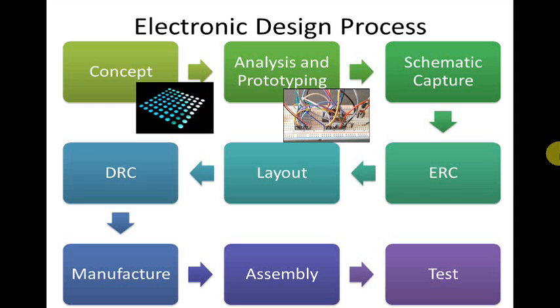This is where we look up the parts we want to use, we breadboard it out, we prove that the circuit works before we start to capture it in a fixed format. The next part is the schematic capture. Once we have it worked out on a breadboard and prototyped, we can put it into a piece of software that allows us to represent it graphically and also allows us to do analysis on it.